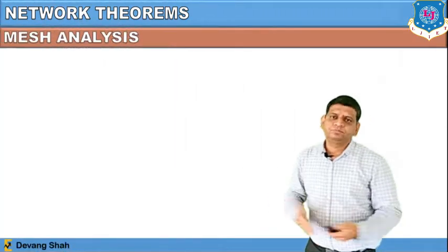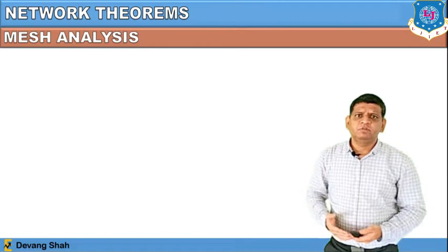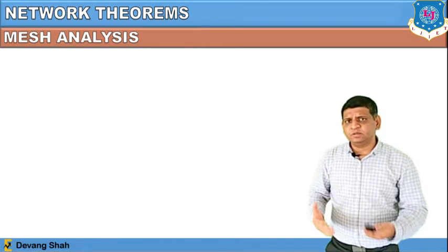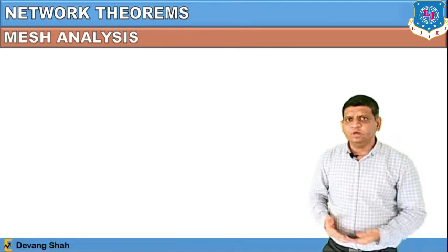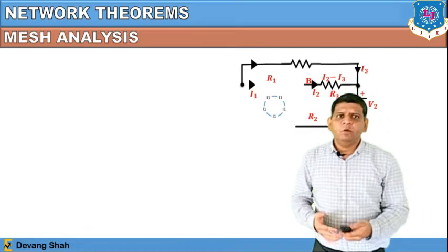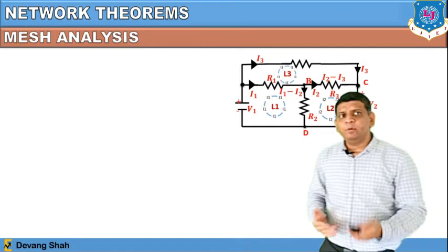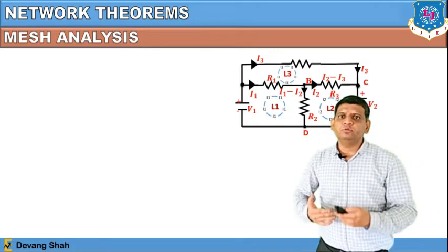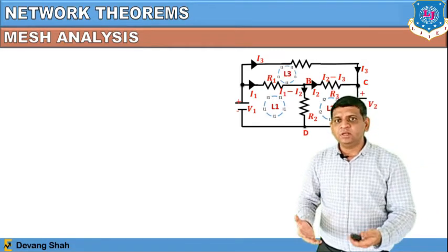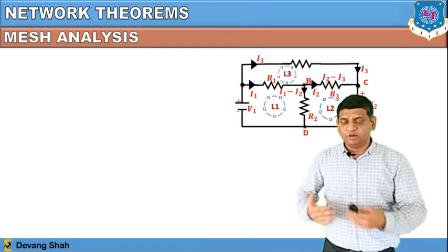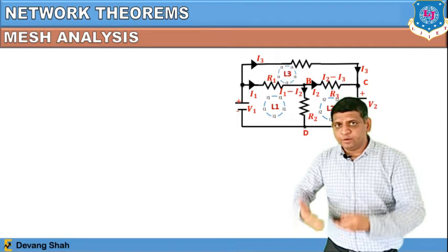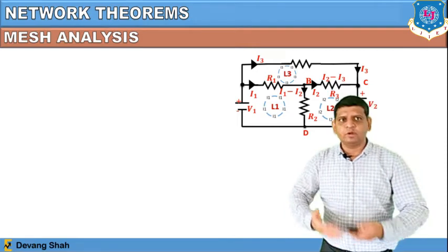Right now, our next important term, which is called mesh analysis, this is nothing but the extended version of Kirchhoff voltage law, where all the terms you consider as a voltage, right? So now for that, what is important here? Important is that your job is to identify the loops. Loops in another sense is a closed path, right? So in our nodal analysis, we identified nodes, but in a mesh analysis, we have to identify loops.